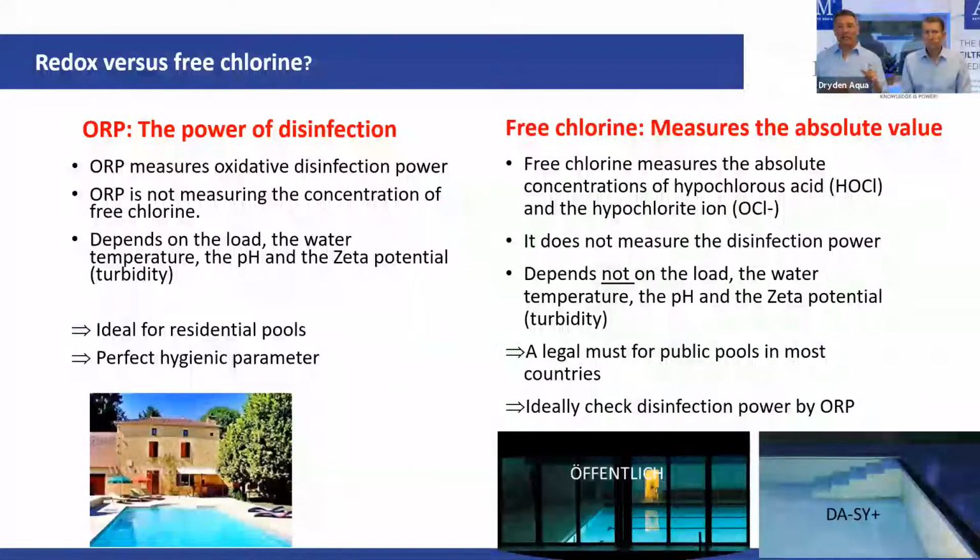Okay, but that brings us to this slide. What is better, redox or free chlorine? It's hard to say. It's something different. ORP gives you the power of disinfection, the red point here, and the free chlorine measurement gives you the absolute value.